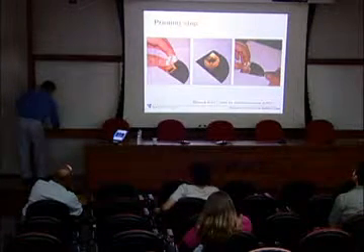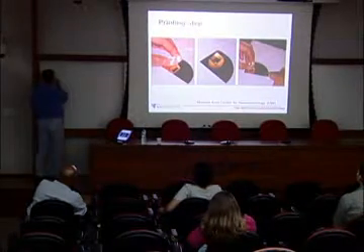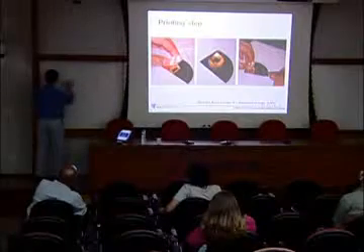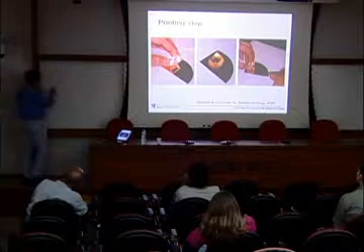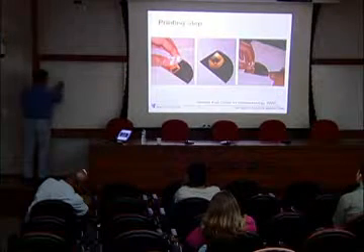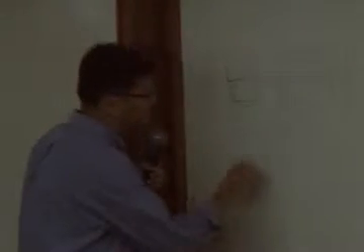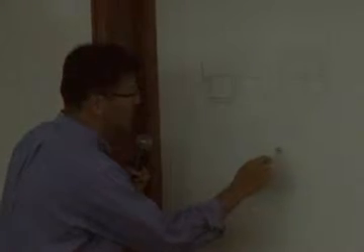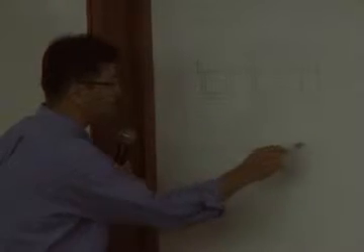When we go down to nanoscale, for instance, we have this stamp with a pattern. And then if you dip this stamp in a solution, then the solution will be coated on the surface. And then it will be transferred onto the surface when we place this stamp on the surface. So this is the pattern that we want to have.